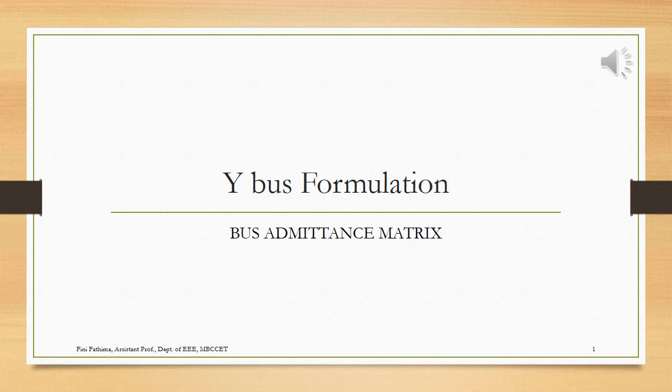This is a very important topic and we need it for all our further calculations. That is, we have to do our load flow analysis and our fault analysis. For fault analysis we will follow the bus impedance matrix, but for the load flow analysis we are using the Y bus matrix because of certain advantages it has got. So let's move on to a 3 bus system.